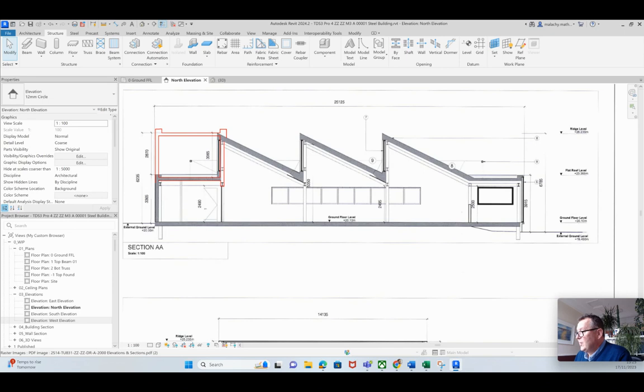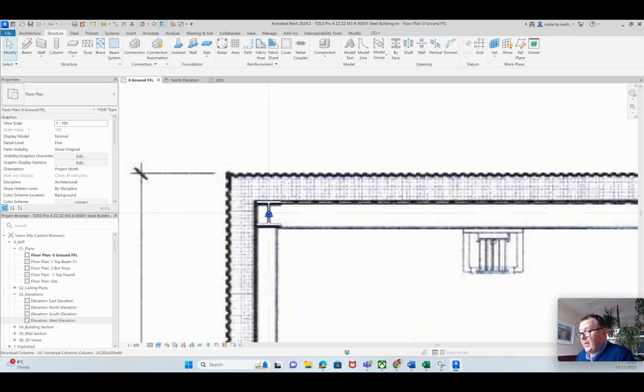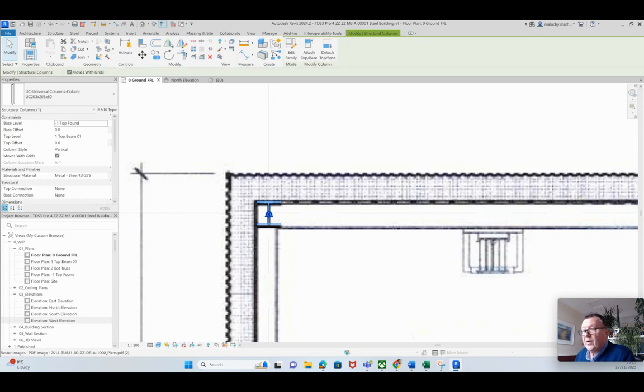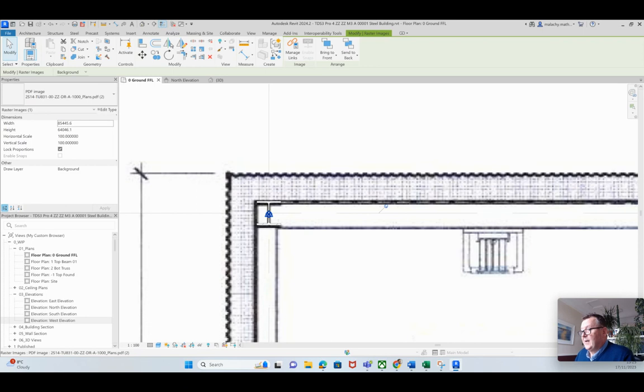Then we've got a couple of lower ones there as well. I'm going to position them, there's not too many of these. I'm going to just position them first, and then I'm going to change the actual height of the column afterwards. All right. So I'm going to pick that, and we're going to put it up to, if you remember, we created the top of truss. All right.